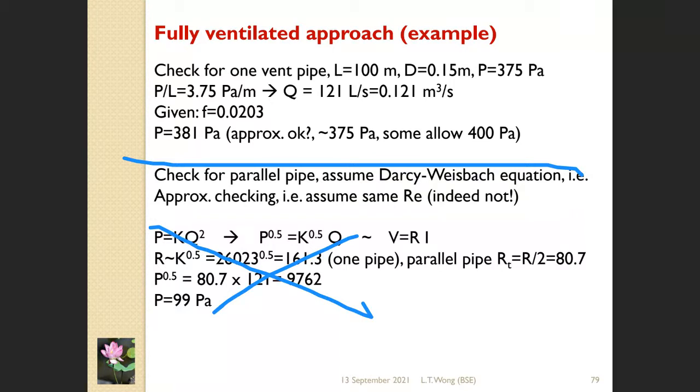And for the ventilation pipe, we have already increased the pipe size to 150 mm. And then the pressure gradient requirement is 375. Why this? Because for the seal trap, the minimum water column is 37.5 mm. There's a minimum. The pressure required in order to penetrate it, to overcome it, is 375 Pa. So then our design is, from the atmospheric pressure to the point requiring ventilation, the maximum pressure drop must not be more than 375. Otherwise, the seal trap will be broken down.